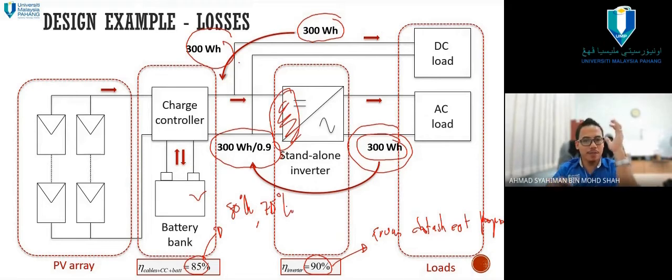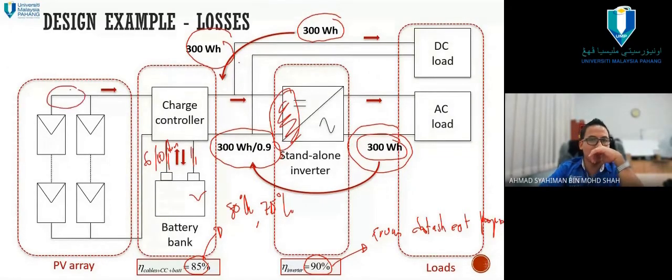Depends, even though maybe you use a battery cable of, who knows, 6 or 10. Usually the battery cable, from battery to battery bank, people use a thicker cable. The original cable for the solar power module is basically 4mm square.